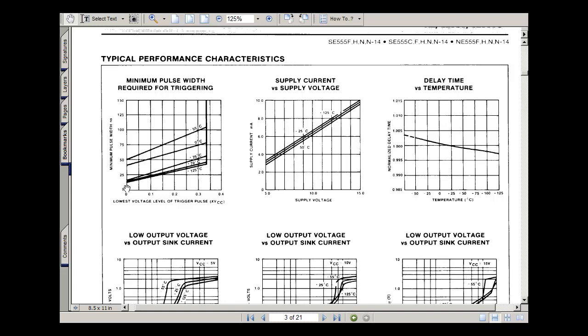I don't need a pulse width as big as 55 or 60 nanoseconds, but something maybe around 20 nanoseconds or so. It's very dependent on temperature, so that's very important to keep in mind that if you are doing something that's going to go outside or go in outer space, you have to worry about the swing in temperature. Silicon can work from -55 to 125 C.